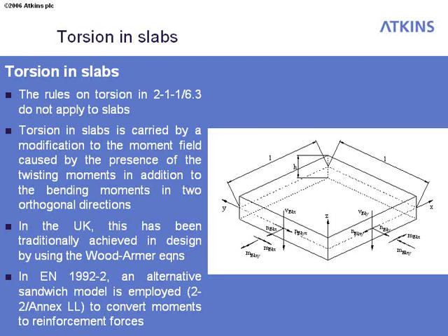The reason it doesn't give it a ringing endorsement is because the Eurocode has a section on what it calls shell models. And the intention is that we should do our design using this sort of shell type analogy. So if we've got a general stress field, such as the one shown here, then the intention is that you actually split this element into a sandwich. So we have two outer layers and then an inner layer.